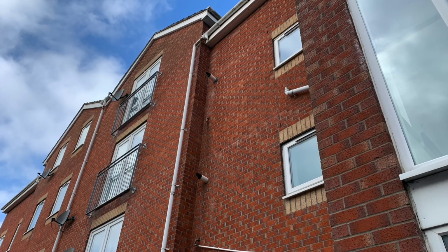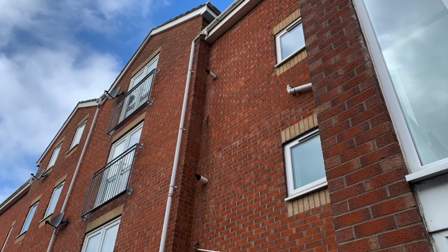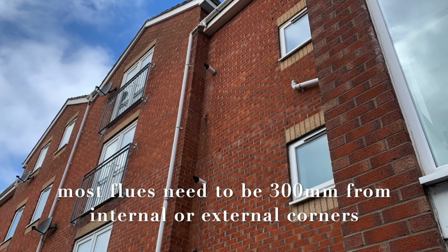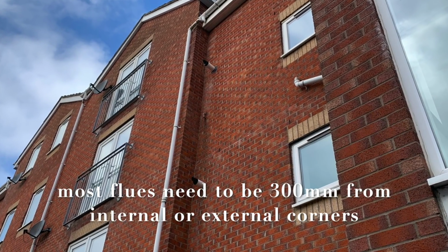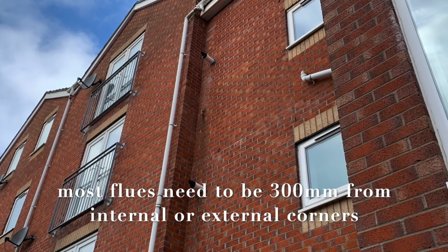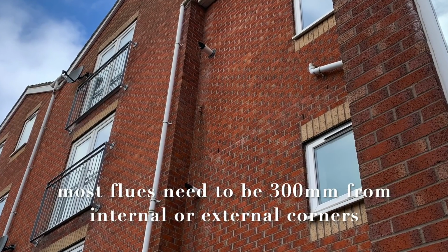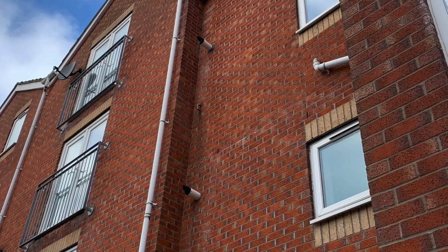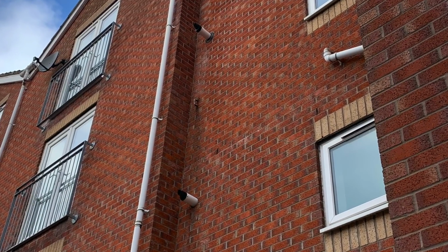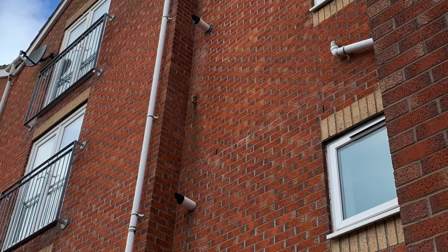And again, we've got flues sticking out here from these two flats, and I guess the engineers stuck the flues out because they thought they were too close to an internal corner, so they wanted to get past the internal corner. But again, this can cause the flues to corrode and could also cause them to be at risk. So again, guys, always follow your manufacturer's instructions and think about where you're siting these flues so you don't have to have the flue sticking out a mile.